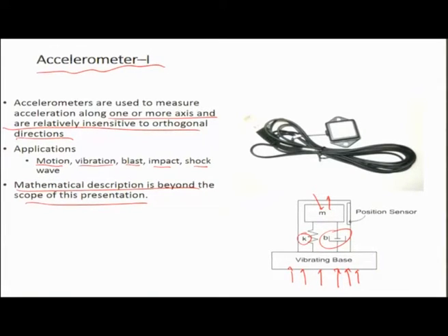Okay, so there is a change of capacitance because of the overlap area between the mass on one side and maybe a position sensor on the other side, which will cause again a capacitive signal. Now the signal is all well calibrated in advance, so you could actually measure vibrations, for example, using such an orientation.